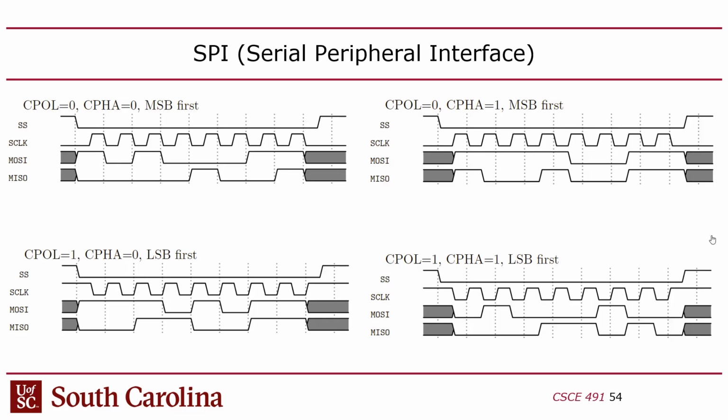So what does this all mean? Well, basically, the only difference that C-fa makes is that the data gets shifted by half a clock cycle. That's the only difference. The timing of the data is shifted into the future, ahead, to the right, right? However, there's a huge impact of that, because if you set this up wrong, in the best case, your data will be shifted by 1 bit. The data you read over SPI will be shifted by 1 bit.